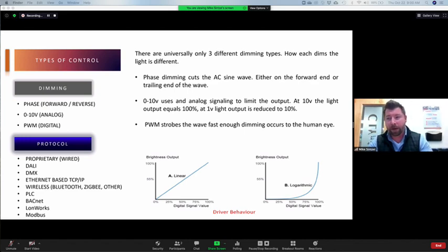So there's not too many drivers out in the market right now that are still solely analog 0 to 10. You can still buy fluorescent troffers. In fact, sometimes they're a lot cheaper to use in elevator shafts. So they'll have fluorescent troffers in elevator shafts or someplace, that if it adds up to a couple hundred fixtures on a project, elevator shaft plus little bike rooms and stuff like that, they might actually specify fluorescent fixtures. So you can still get them.